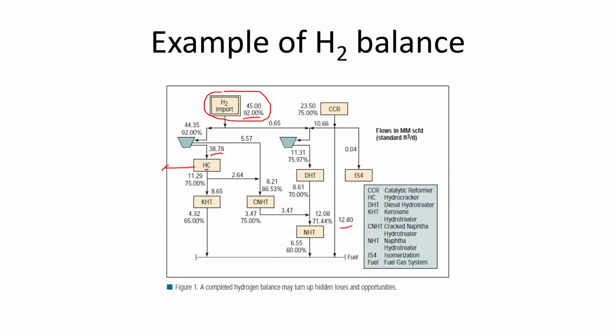It has to have a purge stream, and then it has the recycle stream, which is not shown here. If you go to the plant, you get the purge data and the recycle data. Oh, sorry, it has this purge. I don't know what these streams are. It seems like it's not going to purge, because purge typically goes to the flare. But in this case, it has another line going to the kerosene hydrotreater. So it could be the purge, it could be something else. We have to look into detail how the hydrogen streams are connected in each of these units.